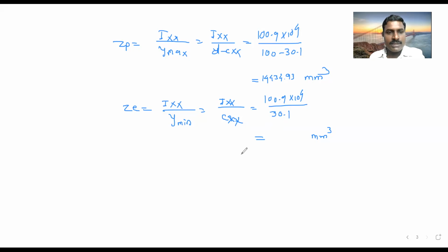So now calculate ZE, elastic section modulus and plastic section modulus. So this is required while calculating the moment of resistance in the next step.